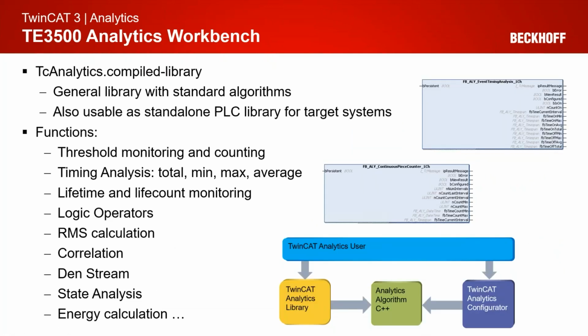What is necessary for that? Necessary is, of course, a PLC library for all the algorithms. Some of you will remember the previous session where I presented the different algorithms that we have, and that we have a toolbox in the configurator tool. And of course, if we want to do PLC code generation, we need a function block in the PLC for each algorithm in the toolbox. And this is done by the TC Analytics compiled library.